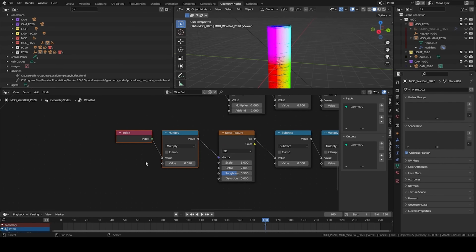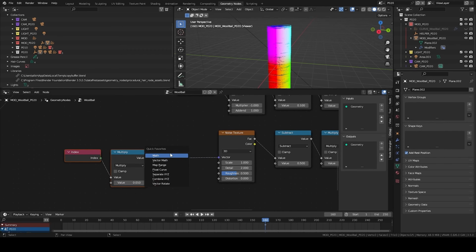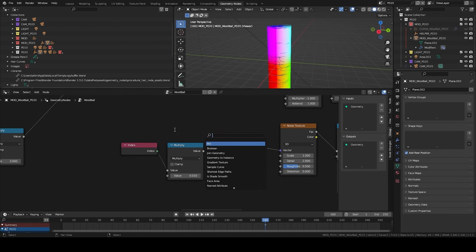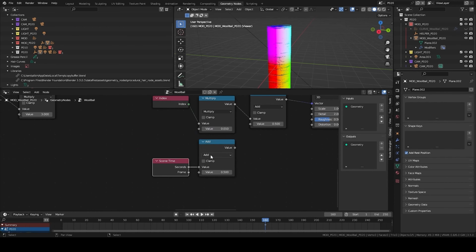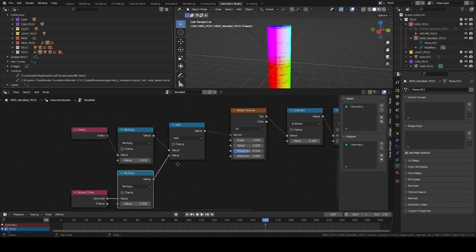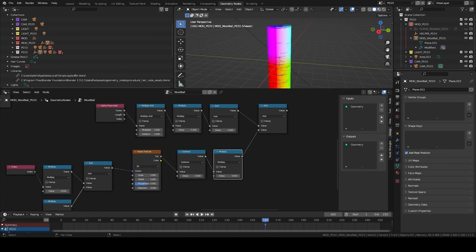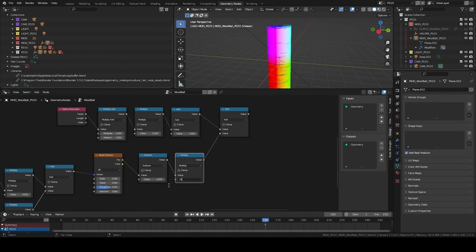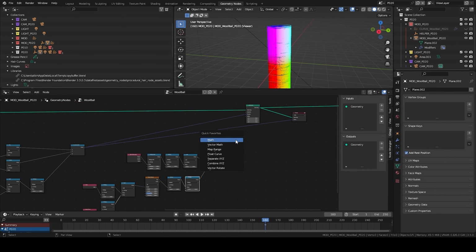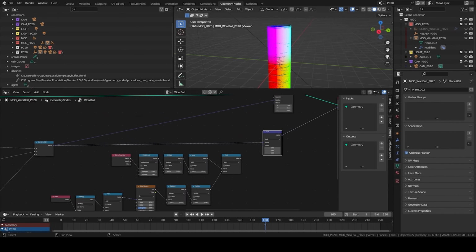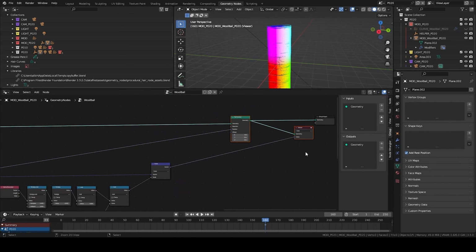On the other hand, as an input, it's not going to be exactly the same. We're going to have an index that's multiplied, but also another element that's added, and that's the scene time, because we're going to give it a tiny bit of movement. And now I connect in the second one with a very low coefficient, and I connect it into the add node. I'll be able to put it a little bit lower, and this time only put 0.1 in subtract. I go and plug it into a vector math that I put in scale. I connect into that position.